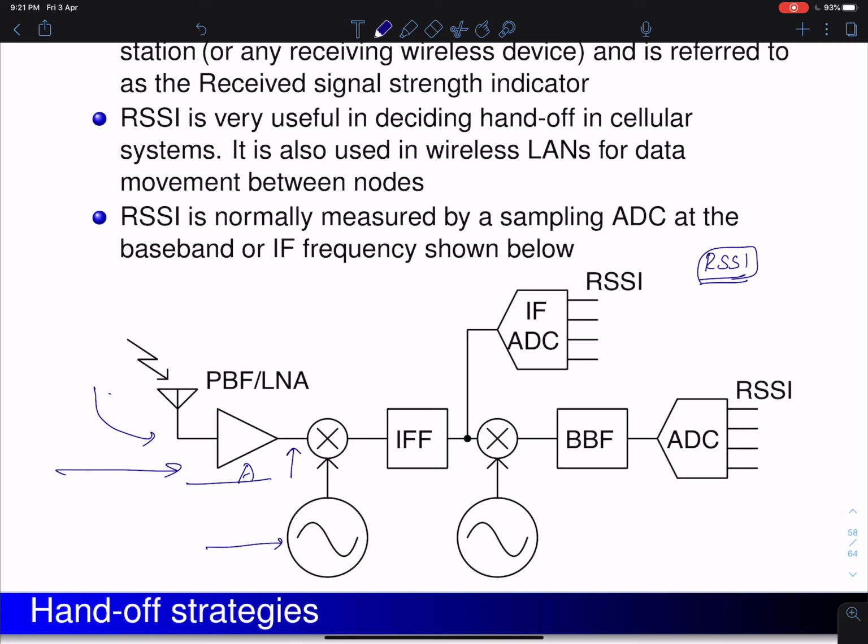Then the next step is demodulation or down conversion. So I'm going to multiply it with a carrier frequency, cos omega 2t. Okay, and then translate. So this data is going to be centered around frequency f1. So first what I'll do is multiply this signal with the carrier frequency fc1. So now once I multiply it, you will get two components, fc1 plus f1 and fc1 minus f1.